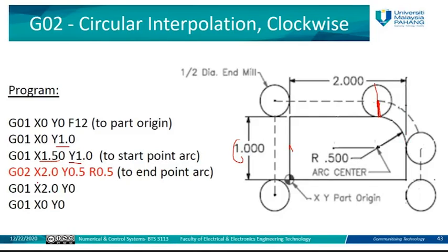Then you need to define the end point of the circular part. So we use the circular profile G02, x equal to 2, and y equal to 0.5.